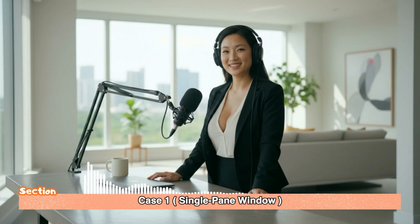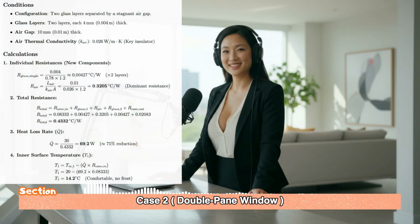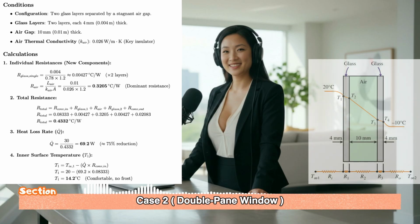And that is the driving force that led to better windows. Which brings us to case 2, the double-pane window. The fix is so simple, and it's all based on the physics we've been talking about, using the insulating power of trapped air. We now have 2 thinner 4-millimeter layers of glass, separated by a crucial 10-millimeter stagnant airspace. The glass conductivity is the same, but the air conductivity, k-air, is a tiny 0.026. So our network jumps from 3 components to 5, all in series: the 2 thin glass layers, the air gap in the middle, and the convection on both sides.